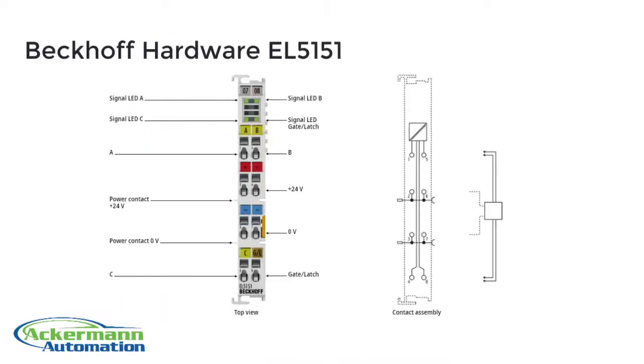The EL5151 is an interface for the direct connection of one incremental encoder with a 24 volts output. It provides the position and also frequency of the encoder. We will use the frequency to calculate the motor speed.